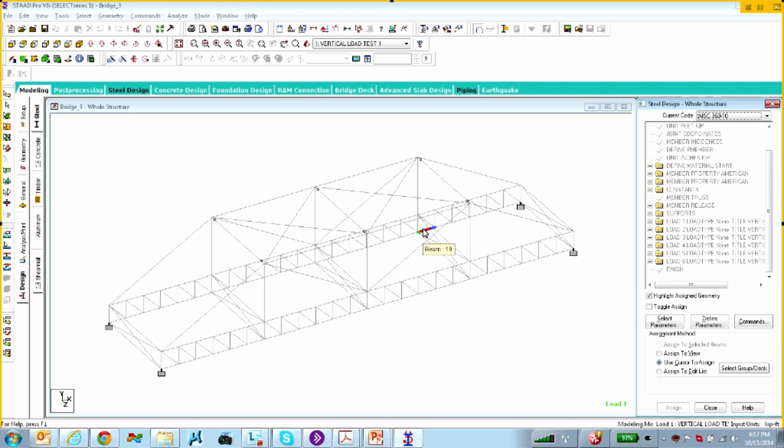If you have a steel rod or something, for example, in your steel bridge, you can always get your member forces and deflection results, nodal deflections and so on, but it won't design something unless it's a standard AISC section. If you're designing something for maybe another class, or you are using standard AISC sections in your bridges, then you can definitely perform a design in STAAD Pro.